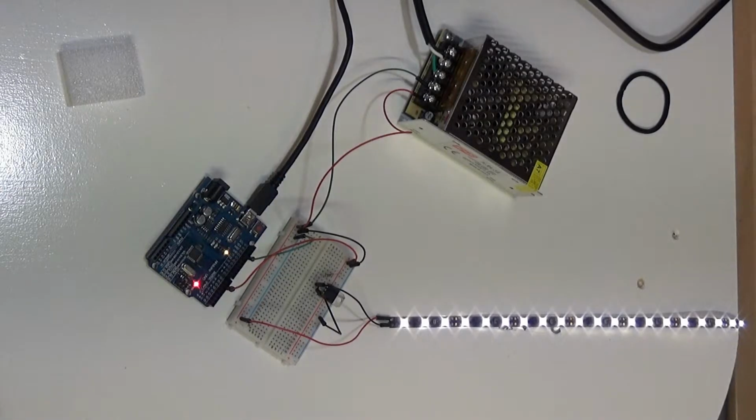Now let's see how to power the 12 volt strip from a controller like the Arduino. First, it goes without saying that we will need a 12 volt power source that will start and stop as needed. To reduce the intensity of the light while maintaining the voltage of 12 volt, small interruptions of current must be made in order to obtain the reduced luminous intensity.